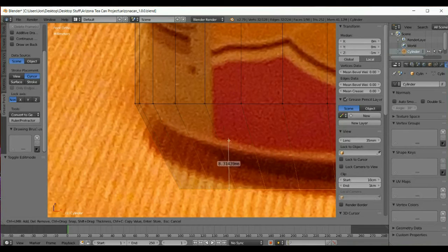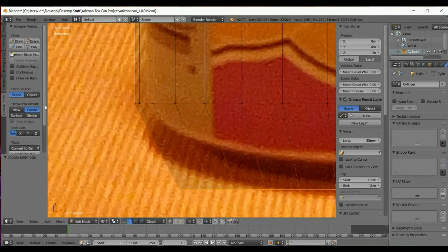So you could say, well, I could put the ruler here very roughly and pull down, but it's very hard to get that into precise position, and I can't save it. If we look at Control left mouse button, in theory that should hold it there, but it actually created me another ruler there. If I undo that, or delete it rather, it sends me back. But then if I escape out of this, I don't have my ruler anymore. If I go back into the ruler protractor mode, it has not been saved. And I've looked this up online, and nobody thinks you can actually do this for real. So the ruler is nice to check your work in rough terms, but it's not actually a precise engineering style solution.